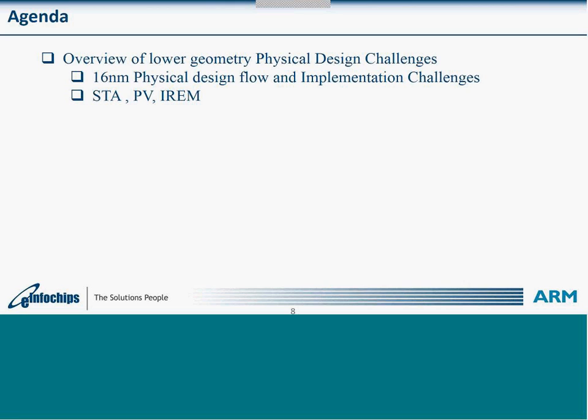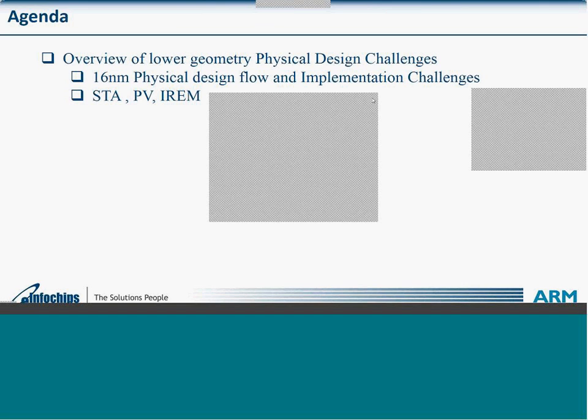This is Nirmit, and Jeba will cover 16 nanometer physical design challenges as well as Cortex implementation from ARM. Nirmit, I'll cover low geometry physical design challenges targeted for 16 FinFET plus. Here I would like to target first the physical design related challenges, and then sign-off related challenges will also be discussed for a few points.